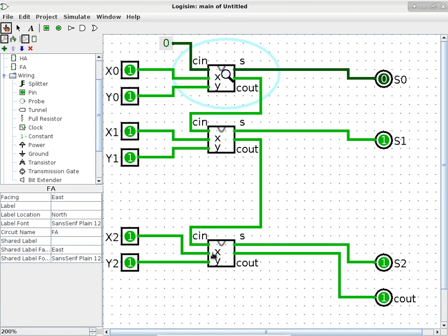So what do you do? Well, you read the rest of that module. Instead of using carry ripple, you use carry lookahead. The carry lookahead mechanism, which is what we will talk about next week, is a mechanism where you can have almost constant time addition calculation, regardless of how many bits we are dealing with. Wow, isn't that a vast improvement